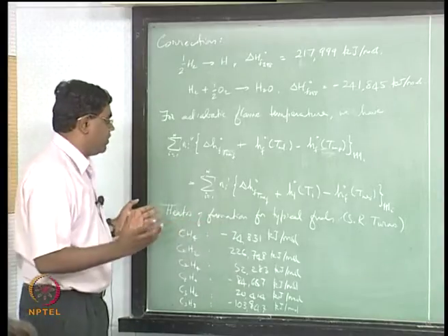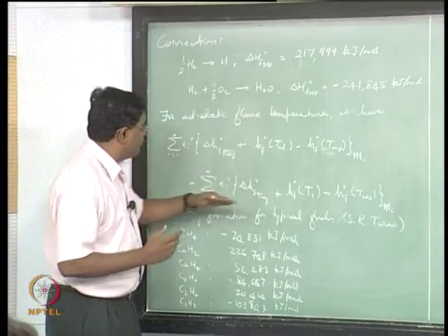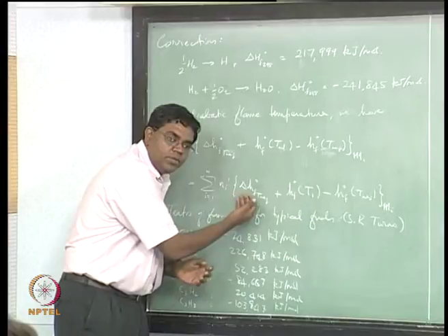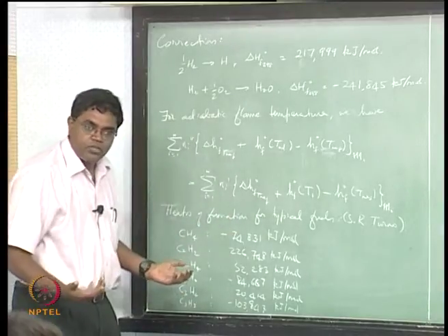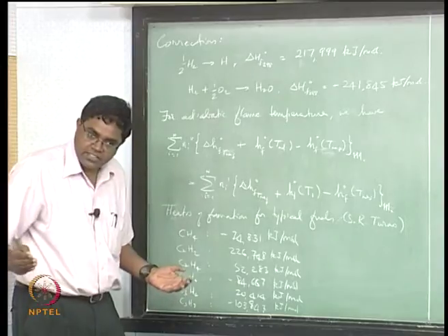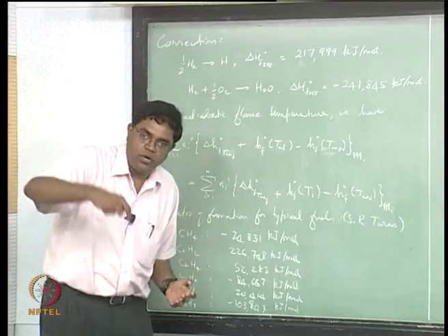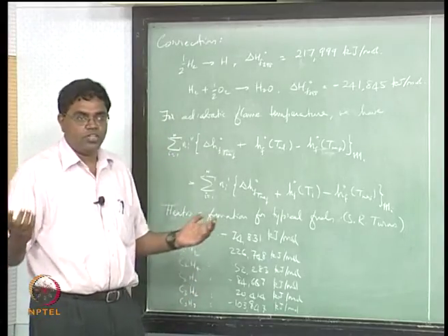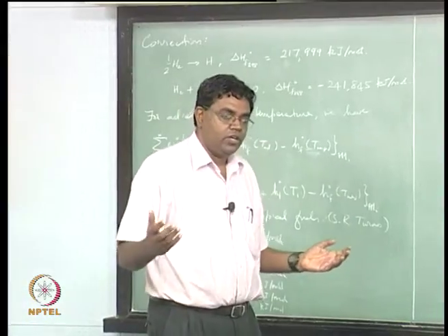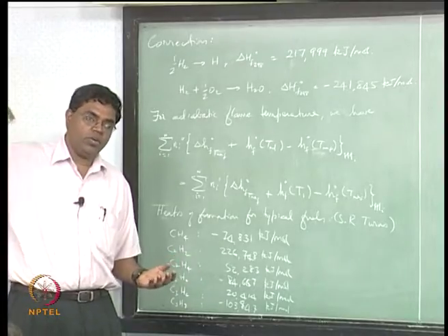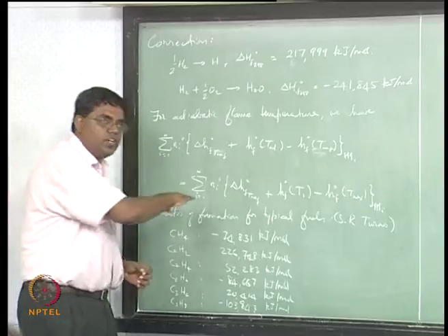So most of the heat was actually available to us in this process. When you try to form the products, you get a lot of heat. That heat has to be balanced, because you have supplied some heat to unwrap the bonds of the reactants to the standard state, so you have to negate that. You got some heat by getting the reactants from their initial temperature down to the standard condition. Let us suppose that the reactants were heated up to 500 K. There is already some sensible enthalpy available with them, which could be taken into account when bringing them down hypothetically to the standard condition.